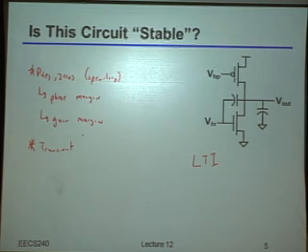Okay? So in particular, again, you guys tell me, if I have some circuit that I know is nonlinear, I know might potentially oscillate, how do you think you would check it using a transient simulation to see that it's not going to oscillate? Or that it's not going to be quote-unquote unstable? What's the typical way you would check that? And again, let's look at the particular circuit that I'm showing on the right over there.